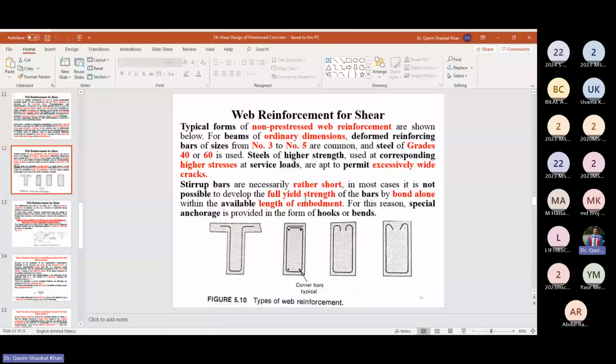That is, if you recall, 60% of the tensile yield strength. So shear yield strength is 60% of the tensile yield strength. If you recall in your undergraduate classes, when you were calculating the shear capacity, you were using one value, 0.6 times Fy. That was to convert tensile yield strength to the shear yield strength, which is 60% of the tensile yield strength.